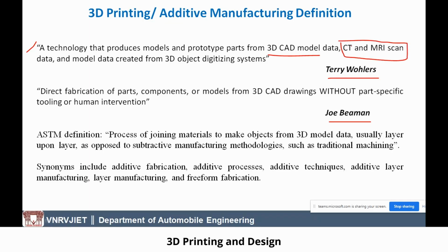or if the soft copies are not available, for example a very old model, and the designs are not available, and it is difficult to draw and difficult to measure the dimensions. In that case, we do reverse engineering. That means we scan the object using 3D scanners, which convert the physical model into a 3D soft copy model, and from that you can reproduce any number of components. So that is a simple definition by